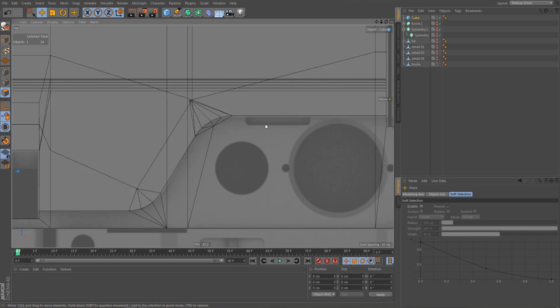And what I can do in order to get that cube over here without having to zoom out is I have my move tool selected and I switch on snapping. And now wherever I click in the viewport and drag my mouse, that object will jump to my cursor. And I'm going to put this cube here and scale it down like this. And I'll make it editable.